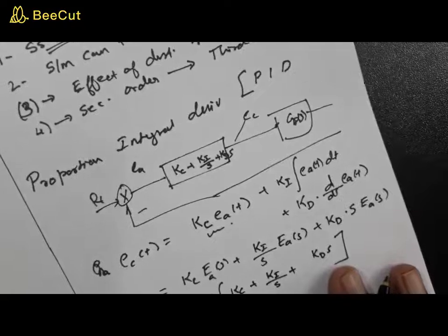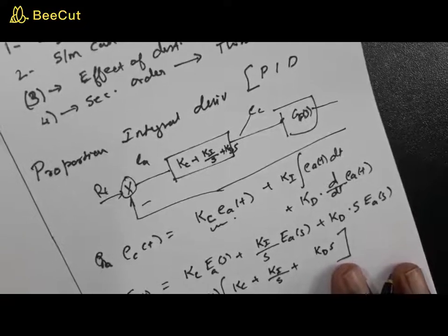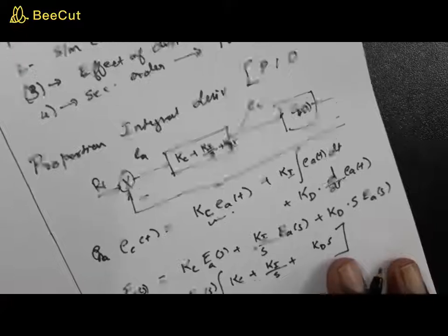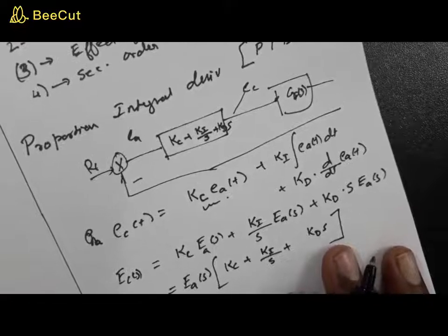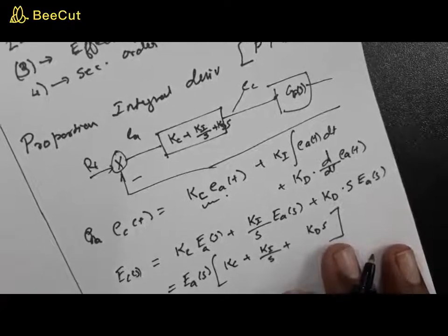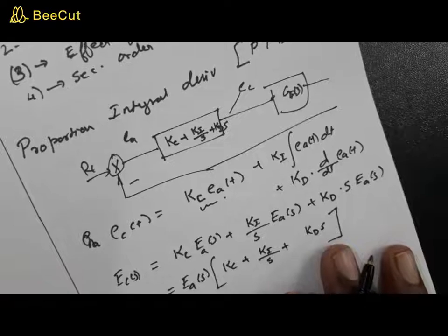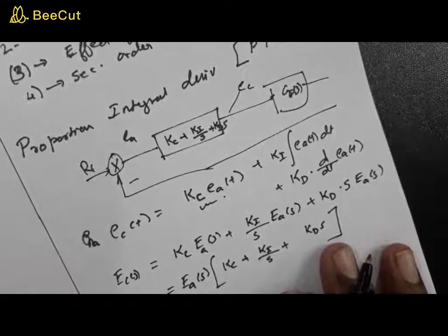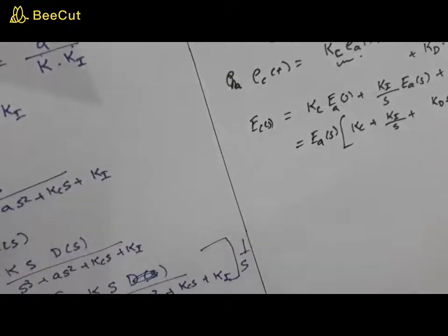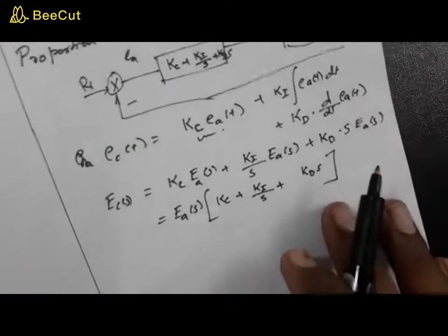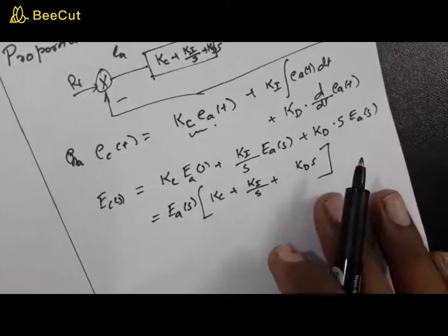Anyway, the advantage of this PID controller is it extracts the advantages of a proportional, integral as well as a derivative. Even if there are drawbacks of each, they can also be minimized by putting some limits. For example, one of the drawbacks we have seen in the integral is, as you increase Ki more, the system can lead to instability.